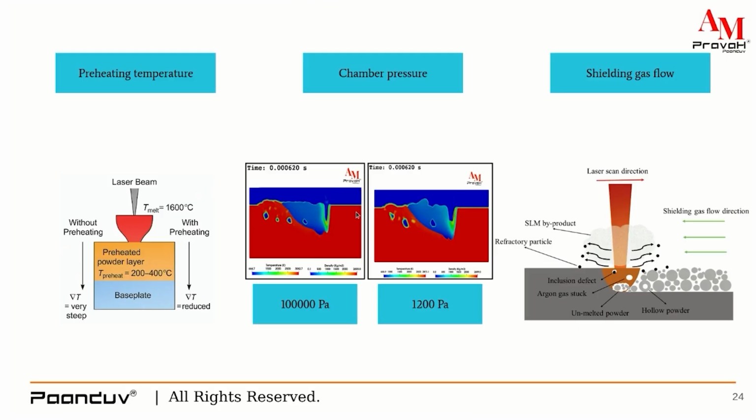But when you go from the smaller scale of the melt pool dynamics to a higher one, you will lose a lot of information. You will get information such as lack of fusion defects, but the fluid flow and the minutest details of the single bead analysis, you will not be able to understand by doing the multi-layer simulations directly. So it is very important to start from the building block of the melt pool dynamics, which is the single layer analysis. These are some examples that we have modeled with PravaH.